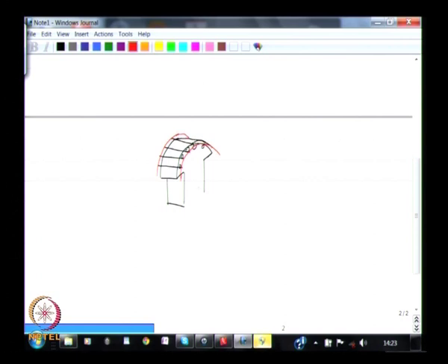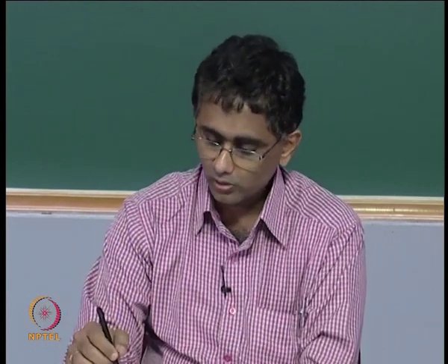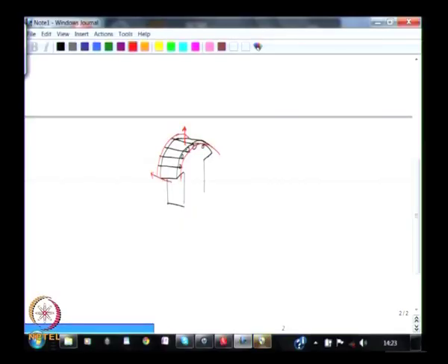Now this will in effect cause some field along the polar axis and some field along the interpolar axis, that is, the field that is produced by this flow in these bars can be thought of as having been produced by a winding on the direct axis and a winding on the q axis as well.